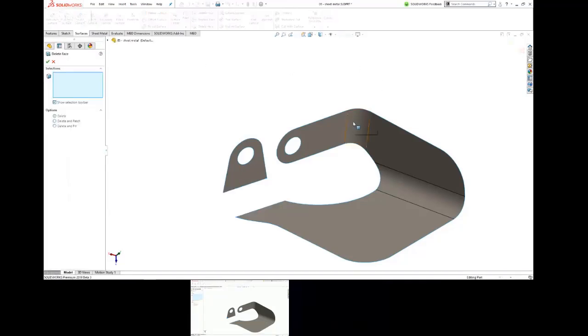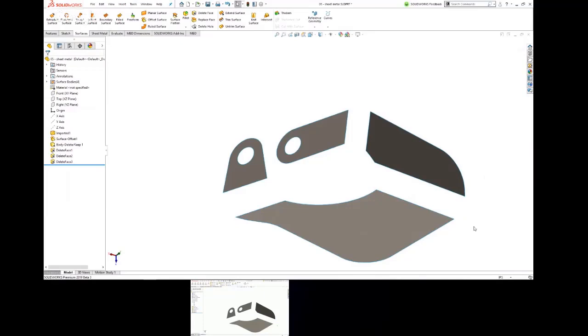Enter key is a good shortcut to get the same command that you just issued. With delete face, I don't think you can pick non-contiguous faces, unless something's changed, but I haven't tested it. Pretty sure I could not do that in one operation. But with that enter key, it makes it pretty quick.